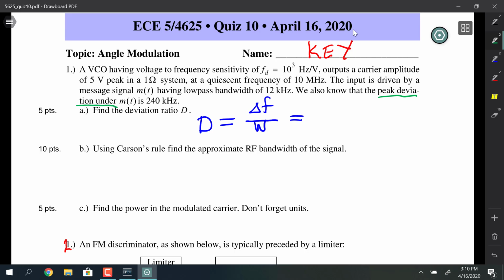Well, the carrier amplitude is 5 volts, so that's where the 5 comes in. That's a different quantity. So if we had a carrier out here, according to the description we have here, we have 5 cosine 2 pi times 10 to the 7th times t plus some phi of t modulation. So what I'd have had to give you is another quantity: the peak amplitude of the message.